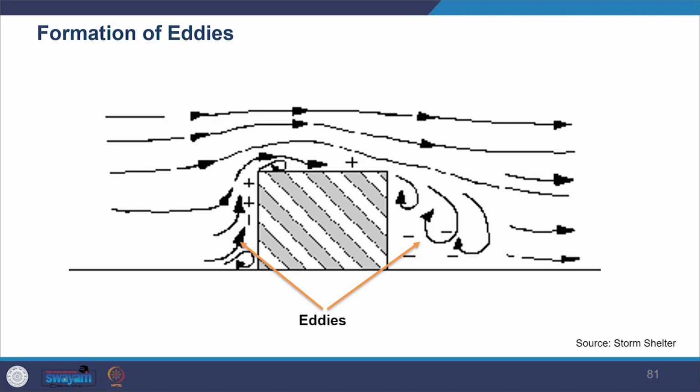So you can see the impact, like how the wind really moves around the building, which causes the pollution to go down. Similar problems may occur if adjacent buildings or hills are within a certain distance, for example 5 stack heights of the release point. So a similar situation can happen. In such cases, the buildings can influence the stack emissions. So there can be a change in the pattern.